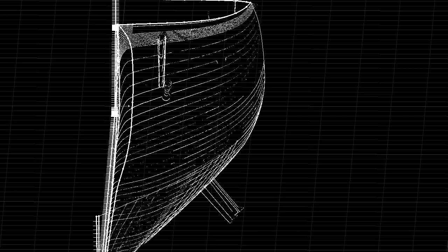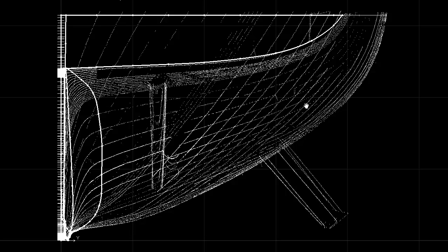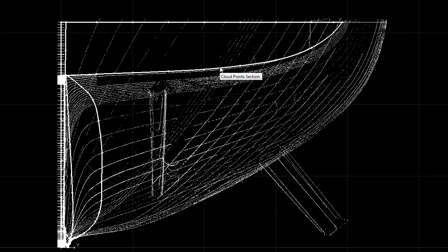We'll now go through the process of generating each of the diagonals for this surface. We'll fit around five curves along the length of the vessel. We'll start around here, and I'm just drawing these curves. We'll create the curve there, and carry on through this process. We'll make sure that each curve has the same number of points.